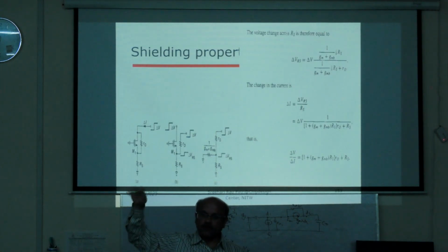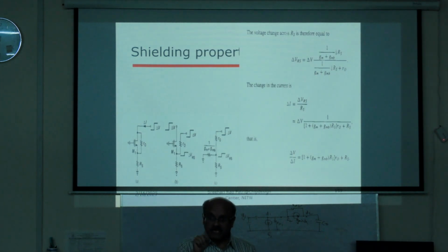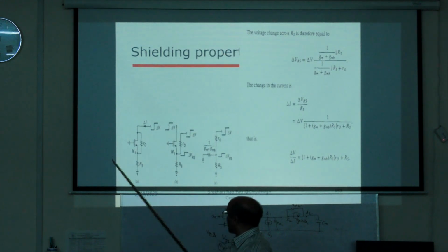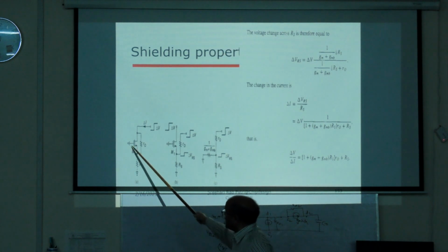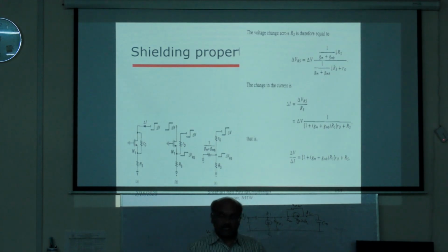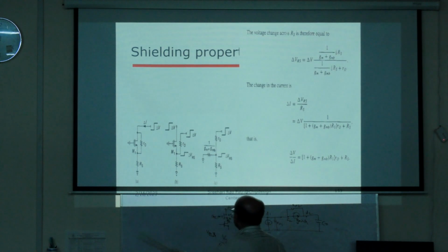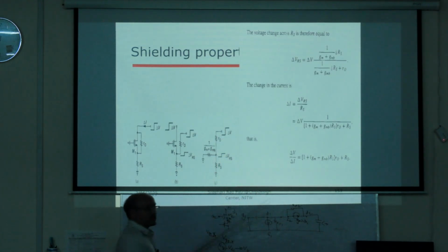So between the output node voltage variations, as I said earlier, if the drain voltage of the driving transistor varies, then its VGS varies, and therefore the current also varies. Therefore we were crying, right? Now that is being addressed. To some extent at least that variation is being arrested. It is not that no variation will be there, but it is acting like a shock absorber. Is it okay? Right, so this is the shielding property of the cascode.